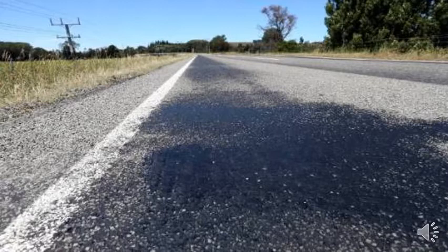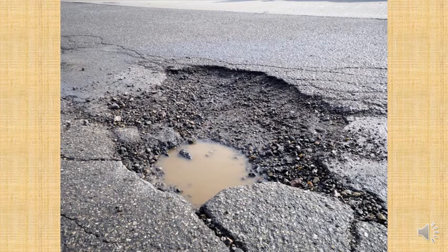That can cause potholes in time, because basically once the bitumen is washed away, you're just going to have aggregate, and water can get in between the aggregate in the voids, and that's going to create big holes underneath the wearing surface of the road. So that's a picture of a pothole.